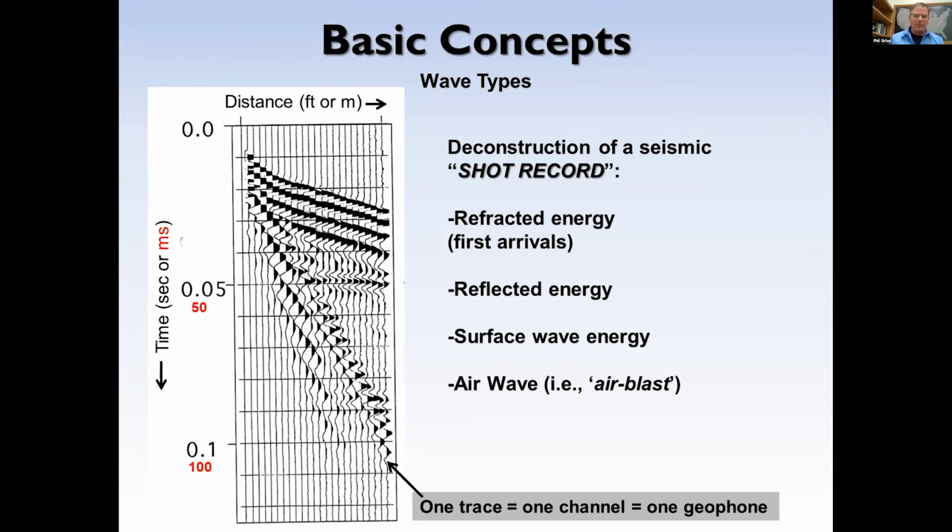We do 120 quite often. And the goal here is just that one of these traces represents one wiggle from one received geophone after hitting the ground. But what we're looking for are things in these waveforms, not forgetting that there's an air wave that travels from hitting the ground. We know the speed of that. It's about 1,100 feet per second. Mariners know the number better in water.